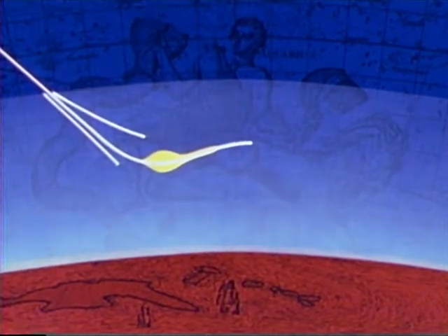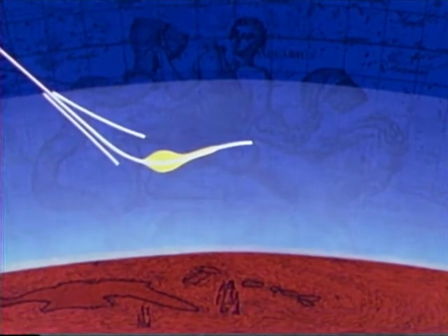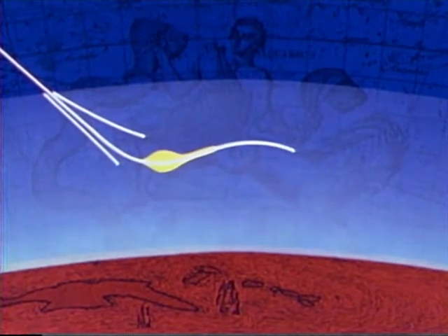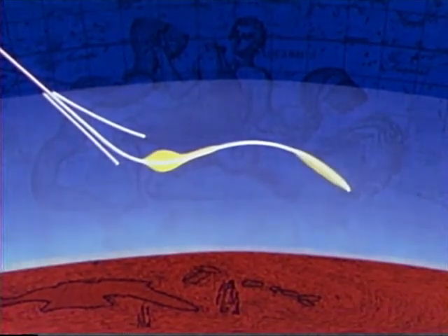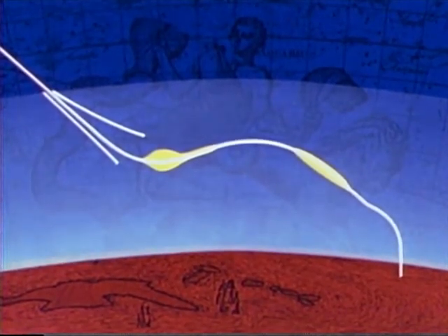The skip is primarily to increase the maximum range of the spacecraft and to reduce the aerodynamic heating load on the heat shield. As the skip is approached, aerodynamic control is reduced to practically zero. During the skip, the crew will be experiencing weightlessness. The skip will not take the command module beyond the 400,000-foot level. It will then descend, starting its second entry, and go on to the second control period. The entry phase is terminated at the 23,500 foot level, at which point the drogue parachutes are deployed and the spacecraft is committed to its landing point.